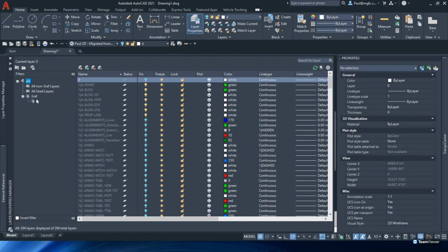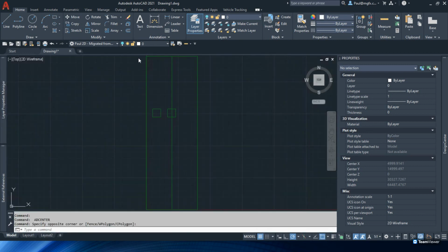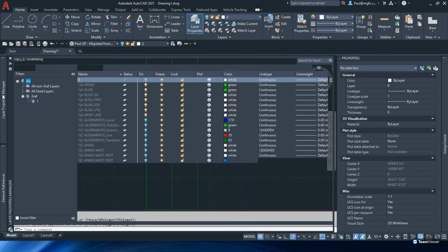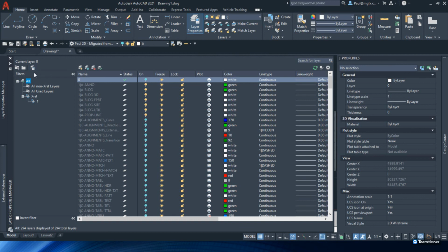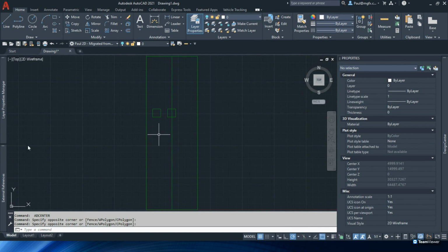Let's look at the Xref layer. Again, you can see that the property filters don't come through. So the property filters are something that's managed within our templates, but the layer states, at least, they do come through. So at best, what one would be able to do is use property filters within the Xref. If they're common to both drawings, it would make it easy to manage. But then we can encapsulate those within layer states, and the layer states do come through with the Xref so that we can control the Xrefs to a large degree by exercising that option.